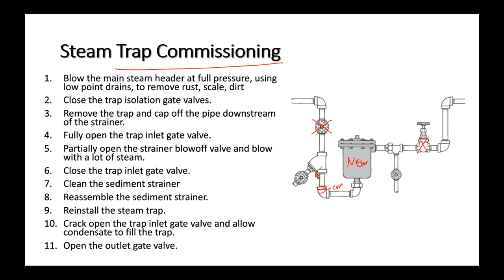And then what I'm going to do is open up this valve and open up the inlet. And I'm going to blast the steam and crud and debris out, because maybe there's scale and rust and dirt inside of this pipe. And we want to make sure that's all clean before it gets to our nice brand new trap. So after we blow it for a reasonable amount of time, then we're going to close this valve and let it cool off.